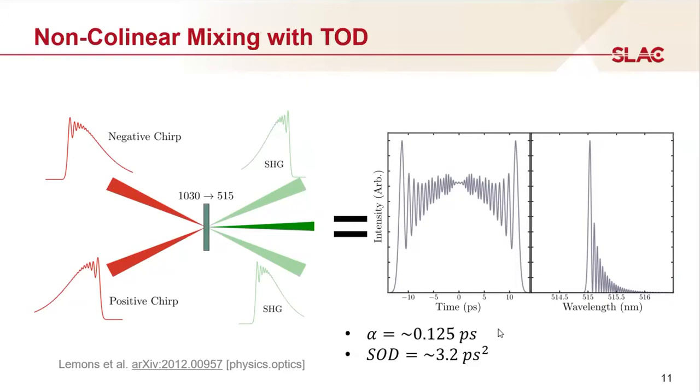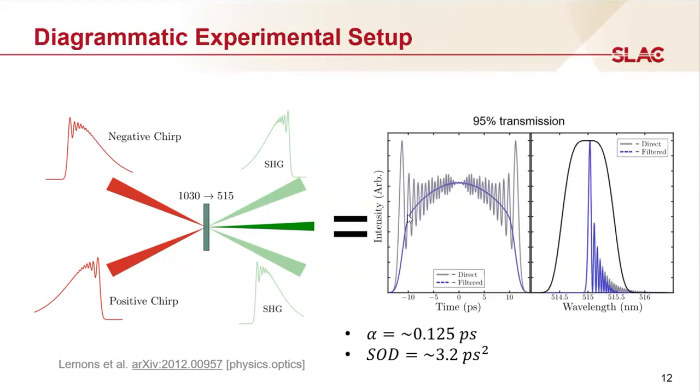However, one interesting and redeeming quality is that the ringing is symmetric and focused on the edges of the pulse. This shape is reminiscent of the ringing that shows up with the Gibbs phenomenon. And indeed, we see that the spectrum has a long tail of higher and higher frequencies contributing to the pulse shape. By applying a wide spectral filter to dampen these, but not the main lobe, we can improve the pulse shape drastically, all with only a 5% reduction in the overall power.